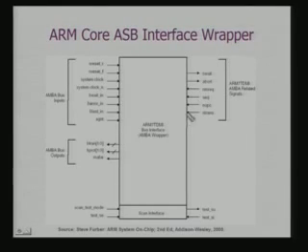Similarly, you have the sequence signal, which tells you, as we used to see, how this can be used for accessing DRAM in a burst mode where I can get data from consecutive locations after selecting a row. This would be used in defining what kind of transaction is actually taking place.